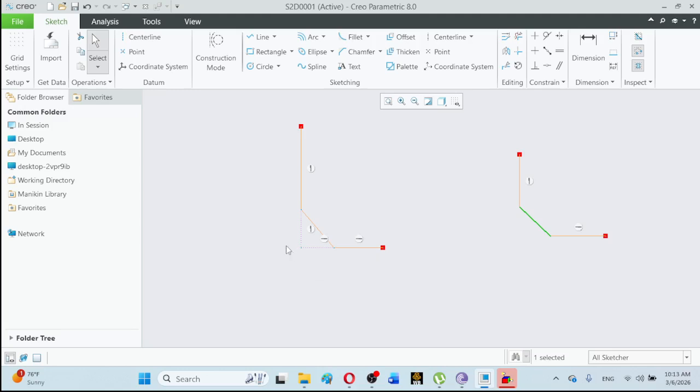it can be added. For example, I can say I have drawn this circle and I want this point to be located at this point. So here I can apply, for example, this coincident constraint like this, and as we can observe here,